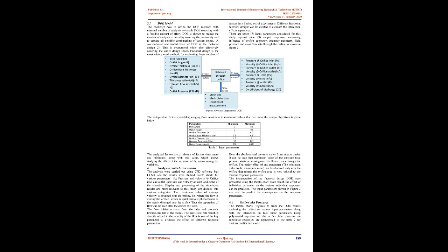The polyhedral mesh is selected as it is numerically more stable, less diffusive, and more accurate than an equivalent tetrahedral mesh. Moreover, it also contains approximately 5 times fewer cells than a tetrahedral mesh for a given starting surface. The prism layer meshes are generated next to the wall boundaries to improve the flow accuracy for the enhanced calculation of several flow features such as pressure drop, etc.